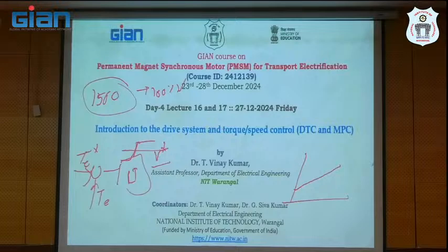Right? Once speed is accelerating, then further you have to increase the voltage. Once back EMF is coming closer to voltage, further you can increase the voltage again, 20%, 30%. You have to give freedom to the rotor. Once the rotor is coming in phase with your requirement, then step by step you can accelerate. This is what they are doing in the laboratory in Siemens drives applications. In open loop, most of the drives in Siemens operate with open loop, only a few drives, whenever high dynamic performance is required, operate with a closed loop mechanism, right?